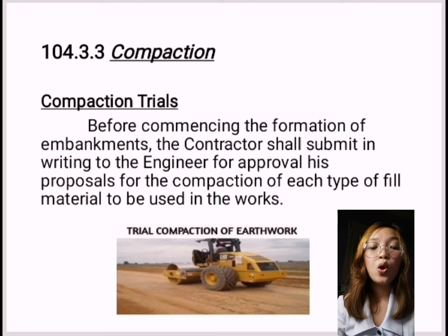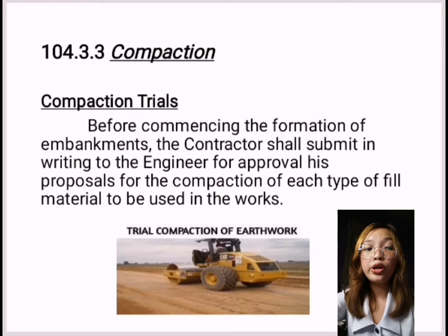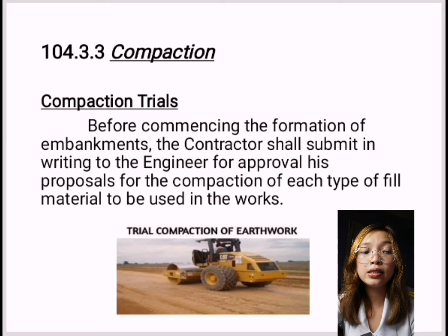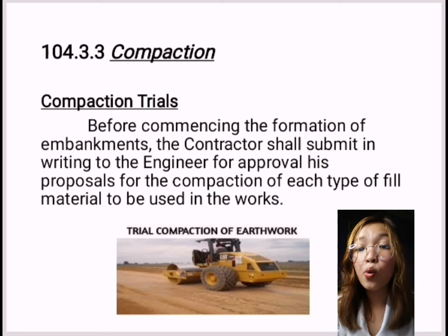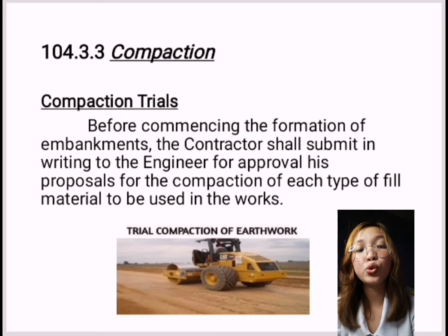Next, let's proceed to item 104.3.3, or the compaction. So under this is the compaction trials, where before commencing the formation of the embankments, the contractor shall submit in writing to the engineer for approval his proposal for the compaction of each type of fill materials to be used in the work. So the proposal shall include the relationship between the types of compaction equipment and the number of passes required and the method of adjusting moisture content.